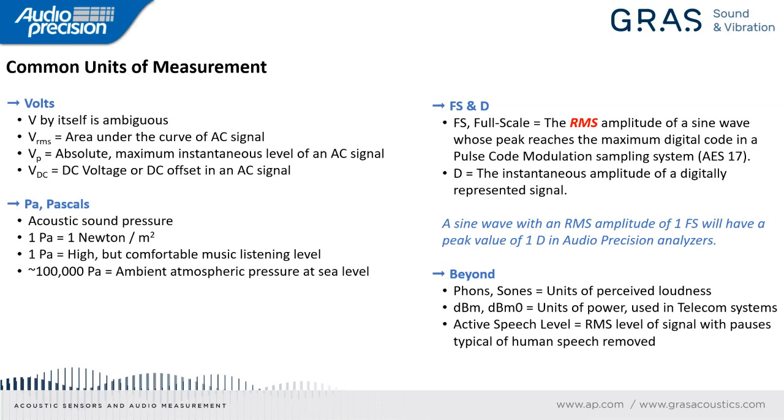At sea level, roundabout, there's about 100,000 pascals of atmospheric pressure. And you can then work out that a pretty high AC signal in terms of sound is going to be really a small signal riding on top of that static pressure.